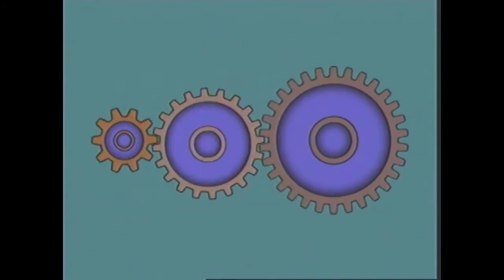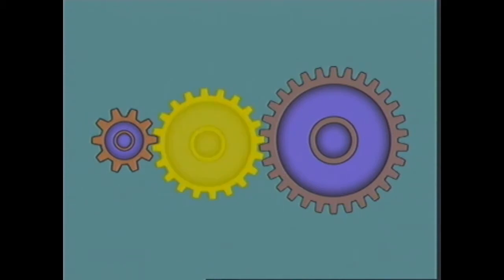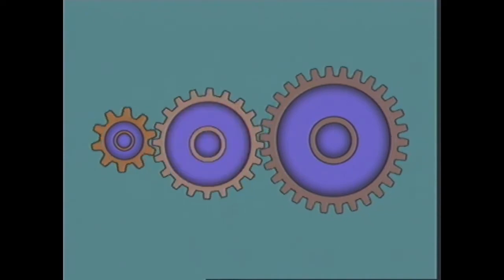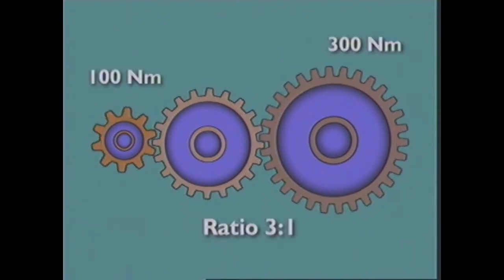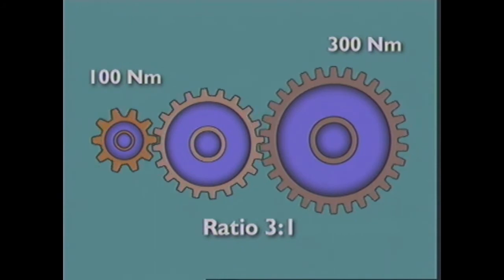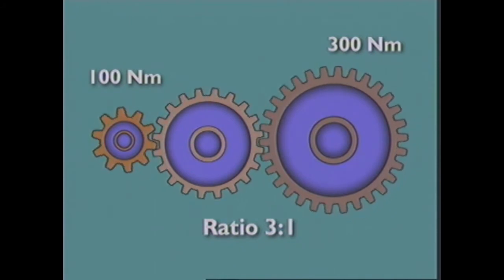When 3 gears are in mesh, the input and output gears are meshed with an idler or intermediate gear. The idler transfers movement between the input and output gears, but has no effect on the ratio or the torque multiplication. These remain unchanged.